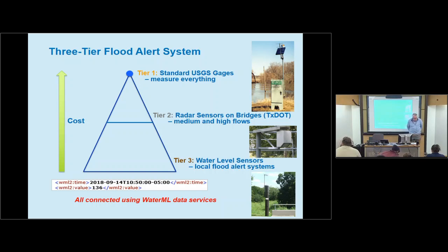So I would say one thing. There's a lot of uncertainties in this. Some of them we've mentioned. There's a lot of information that is being gathered as we observe things like the big flood in the Llano River. I think there's information in these floods that can tell us about the uncertainties. If we are, for example, getting a calculation from HAND that's different than what's actually flowing in the river, that tells us either we've got Manning's equation wrong or we don't have the hydraulics quite right. We need to be thinking about ways to assimilate that information back into the models to effectively learn better what the real on-the-ground behavior is. I think that's a challenge that's out there, and there's a lot of opportunities for research and improvement that people should think about.